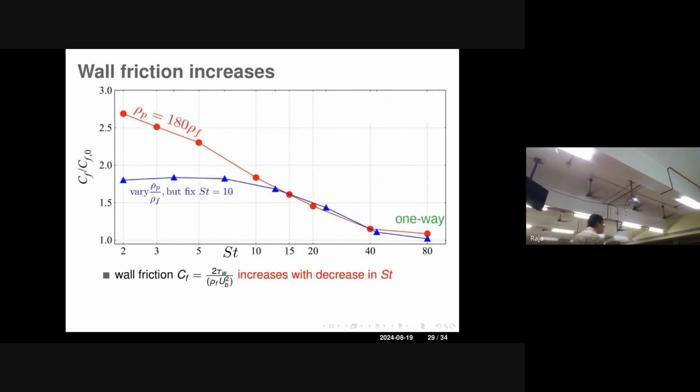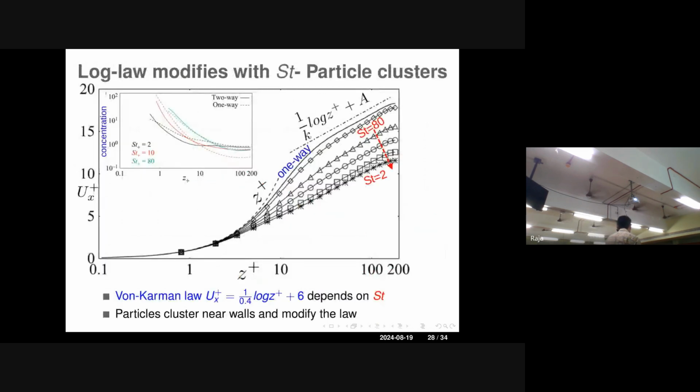Yes. Here, the Stokes numbers are based on wall units. That means at each layer level, we calculate the representative Stokes number. Because as we go layer by layer, your entire wall units are going to change, your local velocity components are going to change, your local length scales are going to change, in terms of the Stokes numbers we are talking about. It's not that the Stokes number is constant throughout this system.